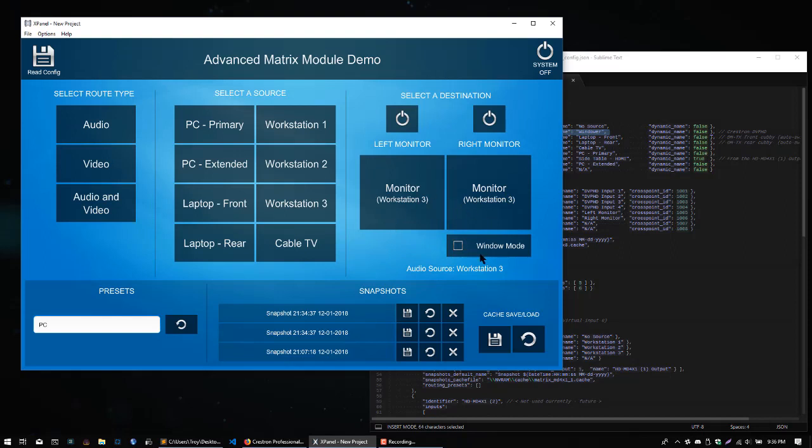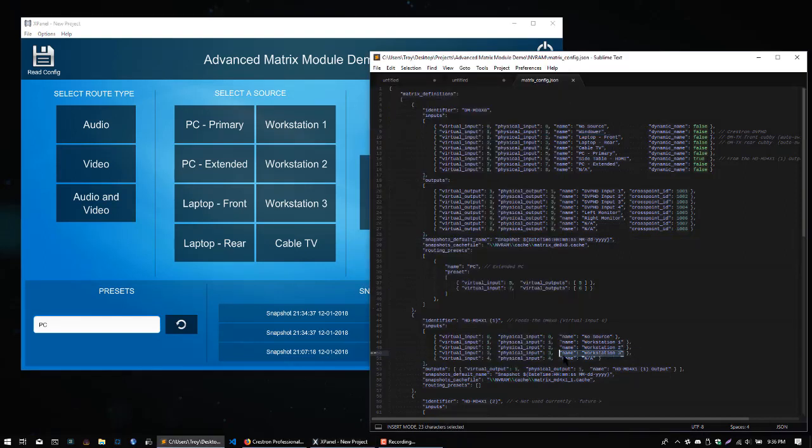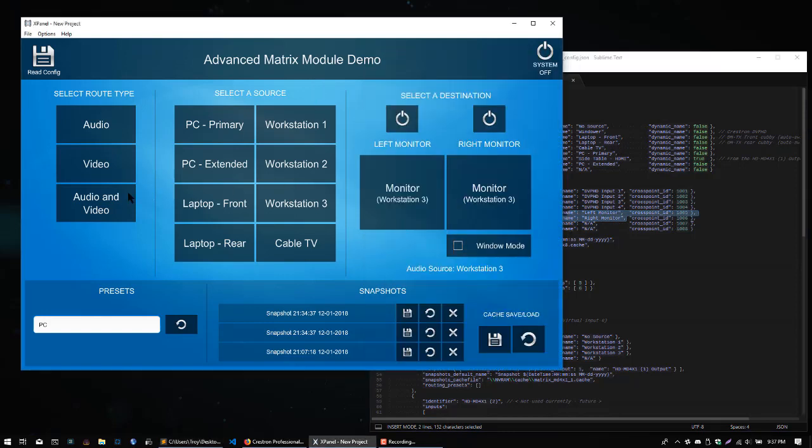So you've got them both on 3 now, because it needs to switch this output to workstation 3, so that single output, it's only one source, it feeds the 8x8, and then it goes to one of the outputs, or both, for the monitors. So everything is kept up to date with whatever you route. Same with audio. There's only one audio path, and that's the HDMI out of the 4x1 into the 8x8 switch. But with everything else, you've got full range, because these are direct inputs on the 8x8, so you can route one there, one there.